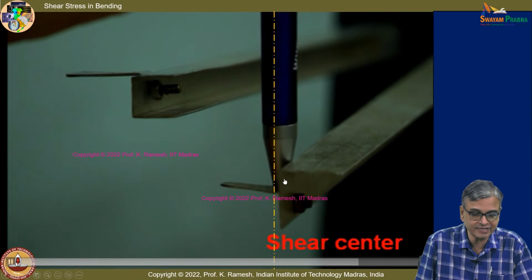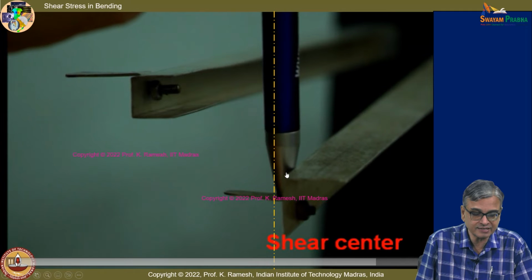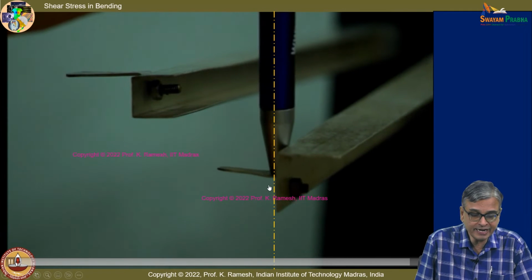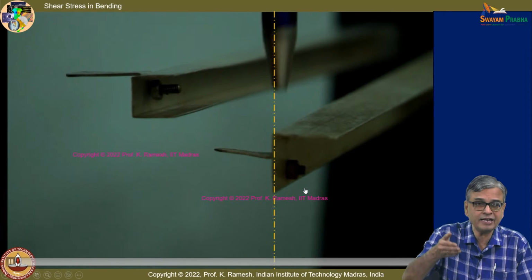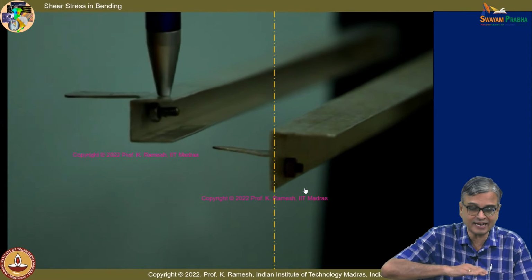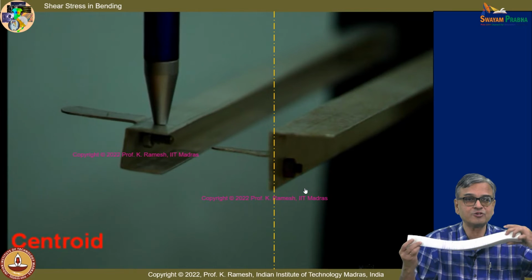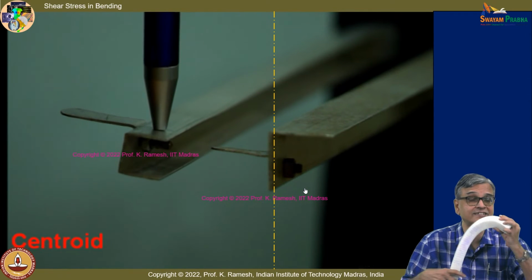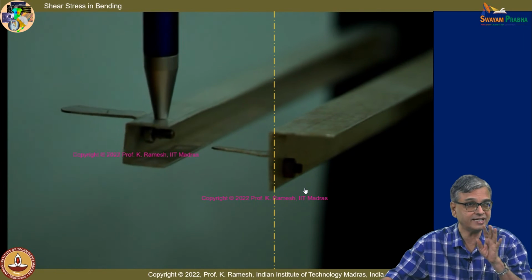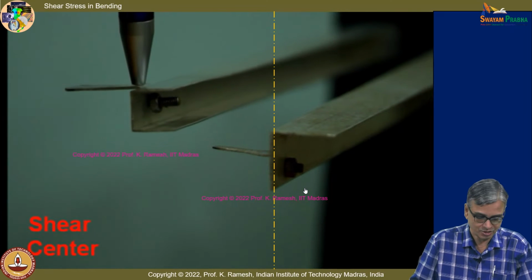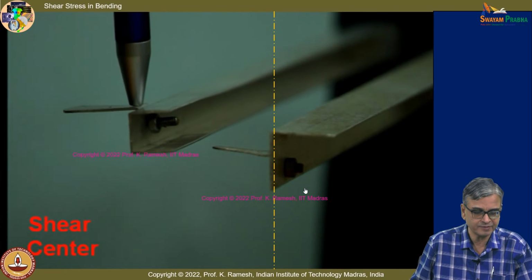You can very clearly say that this is only bending, there is no twist, but while bending, it has bending in two planes. One plane is like this, another plane is like this. It is bending like this, it is also bending like this, and that we said is unsymmetrical bending. Is the idea clear? When it is bending in two perpendicular axes, you have this as unsymmetrical bending.